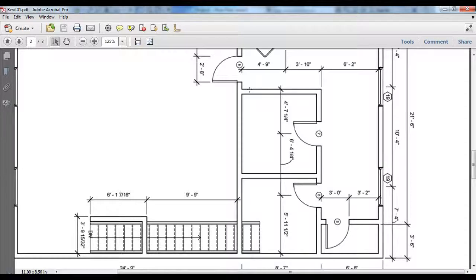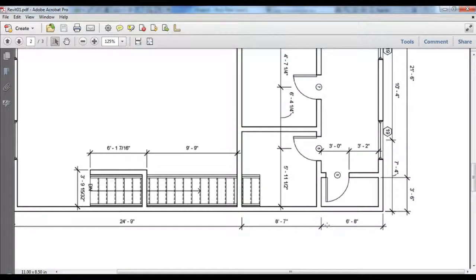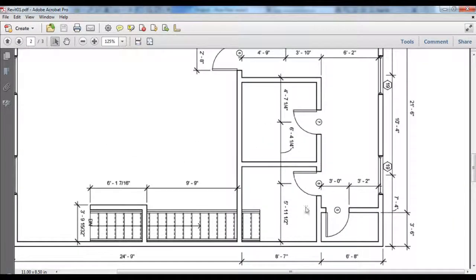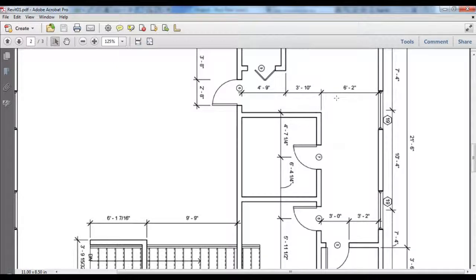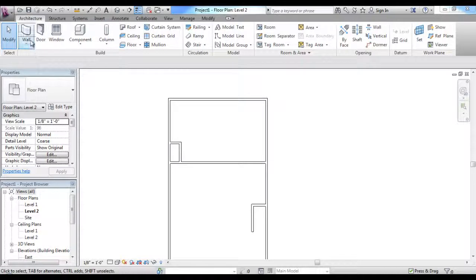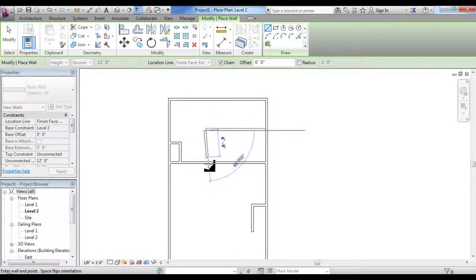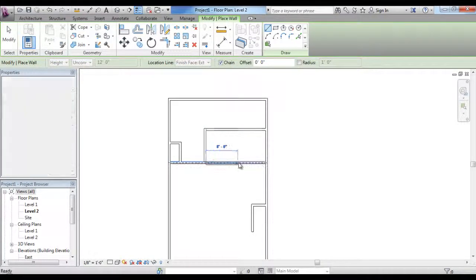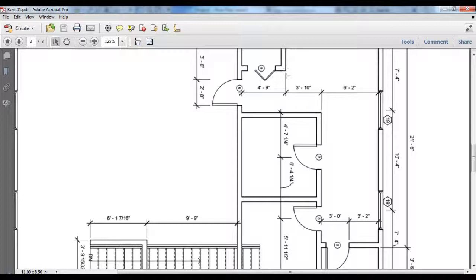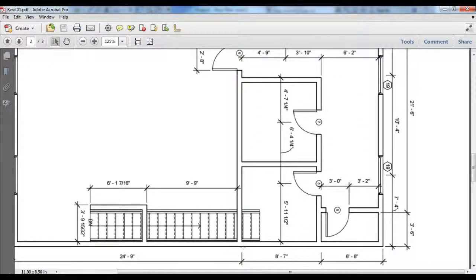We're now going to be adding the closet. So that is going to be actually 8'7" out, and then we're just going to draw that across here. Okay, and this goes, by the way, in the middle of that space. So 8'7". Okay, and this is actually 4'10" from here to here. So we're at 8'7" from about here. We're just going to draw a line here and then bring it over and bring it down, and then we will adjust the measurements. So looking back, the measurement you don't have from here to here is 4'10". Okay, and this is 8'7" from here to there.